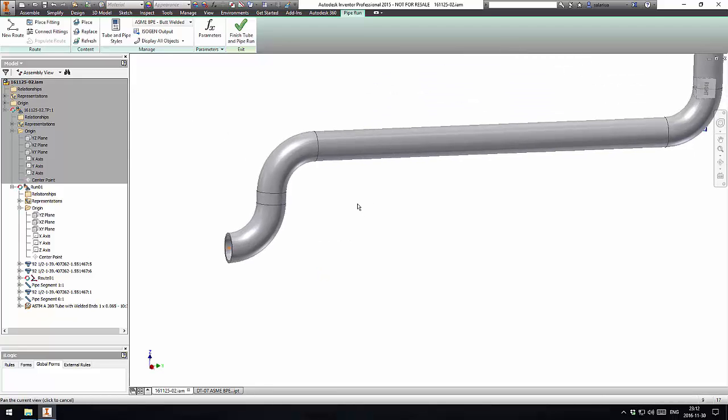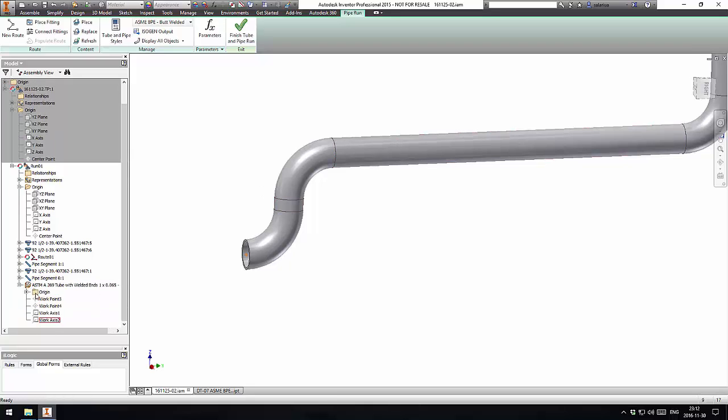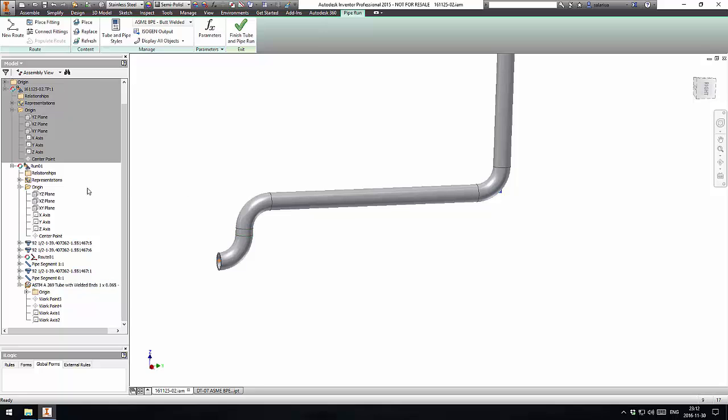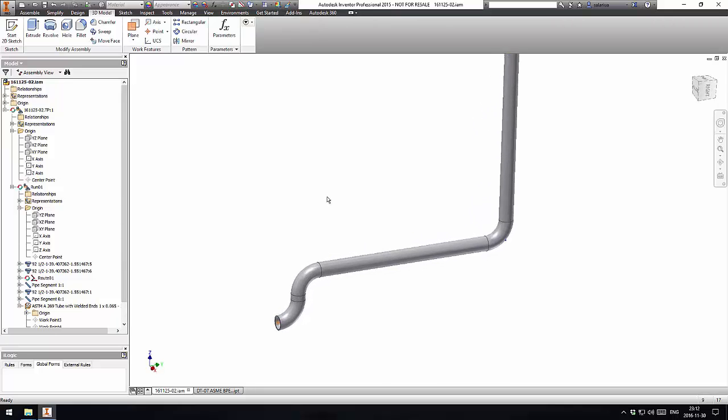And a lot of you will say, well, what's the advantage instead of doing constraints? Why wouldn't I do a constraint, and why would I want to place it like this in here? I hear you, and I understand what you're saying, but think about it. In Tube & Pipe, you actually don't have any constraints. So Inventor is not processing any constraints, is not computing. These are just connected, and they're grounded. And grounded members are perfect. It takes nothing to compute. And that's about it, really.